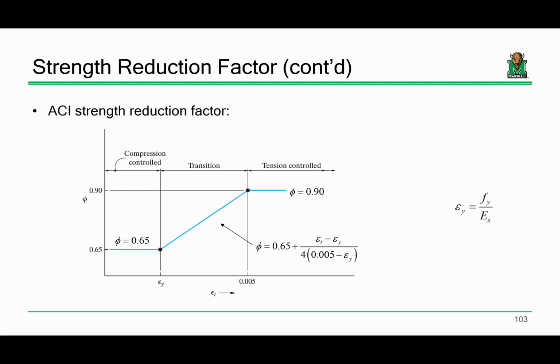So more often than not, that compression steel is there anyways. So you might as well count on it. Now, analytically, we have to determine whether or not that steel yields, but we'll get there. That's something we'll do later, once we do rectangular beams, which is what we're doing now, then T-beams, then doubly reinforced sections. This is good stuff. Any other questions?